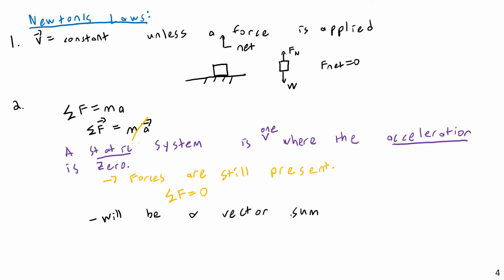So it's not just a matter of simply saying raw amount of force. You can't just sum magnitudes of forces in a two-dimensional system. If you have 3 dimensions, or if you have rotations, we'll be dealing with moments and things like that later in the semester. But for now, we can think of it very simply as the summation of forces being equal